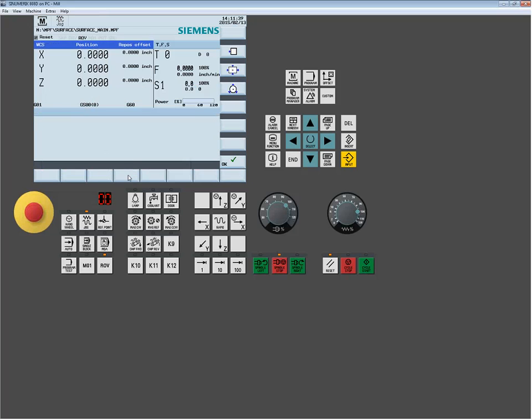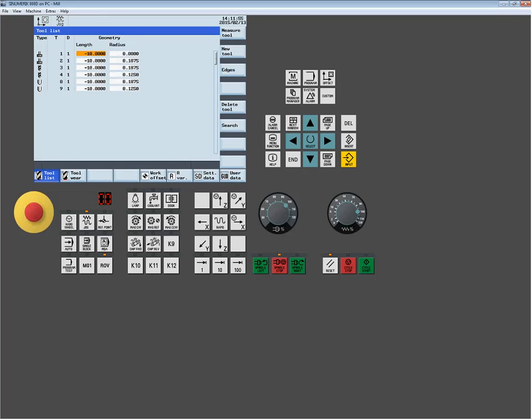From there, I can start to create other folders. Certainly I don't need to use folders. I can have part programs residing right in this directory. As you see here, I have an example one, this MPF file, main program file. But what I am going to do is go into my G290 directory, and this would be the source as to where I want to copy that program to.